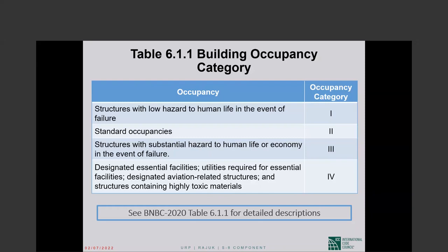In seismic zone 4 or 3, certain structures could not be designed based on equivalent lateral force procedure. The zone brought with it prohibitions on some structural systems, some things you could not do in high seismic zones. Anyway, the zone determined the limitations and restrictions on seismic design, or even what kind of design we could do.